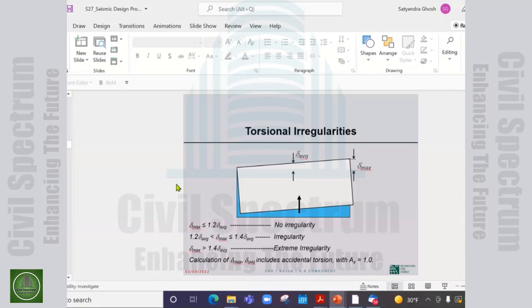To identify soil type like SD, SC, or SA in BNBC, we have to take the average SPT value up to 30 meters. However, if the standard deviation is very high, can we use the average SPT value? This you should ask Dr. Abedin when he comes. I'm not the right person to answer that question.